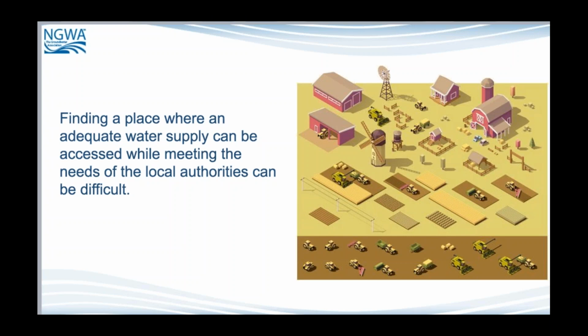Now, if you're doing a variance situation or something out of the ordinary where you can't meet all the local codes and that's the only place you could place a well, doing several of those in a row, usually indicated by two, about 30 days apart or so, and as long as they both come out clean, then you're usually okay, and most variance situations will be approved, and that well can stay there because it was proven that it's going to be an okay situation. Even though it does not meet code, it was still proven that it can be okay at that particular time.